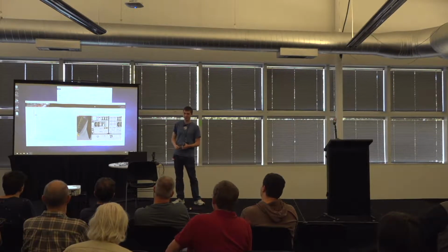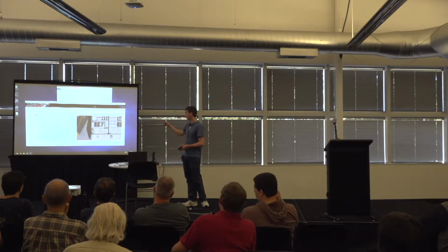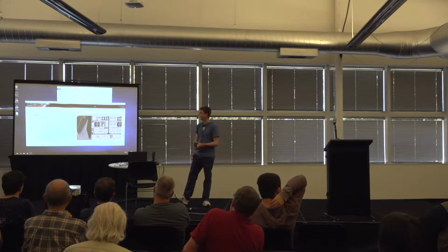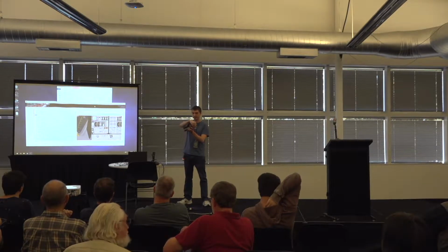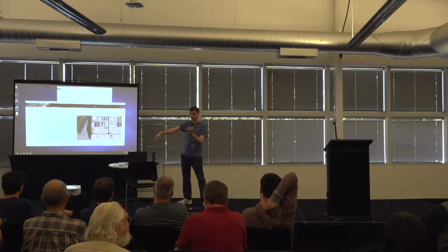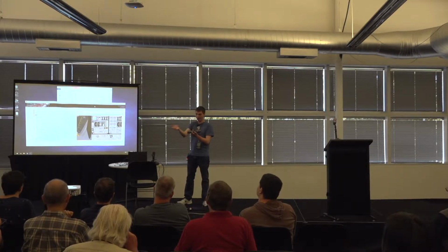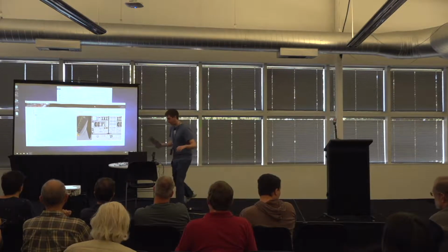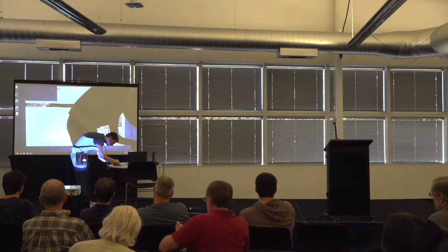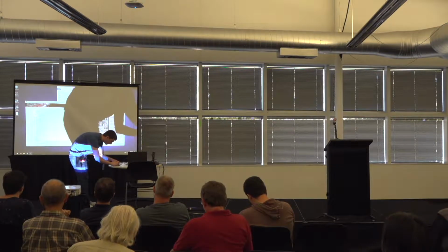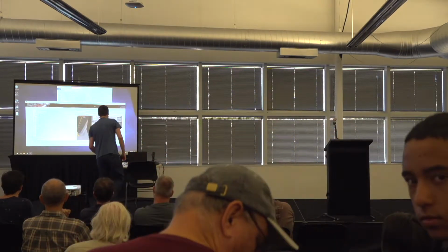NASSP implements the Apollo spacecraft down to a ridiculous level of detail. Most of the subsystems are modeled relay by relay. And normally it runs an emulator of the AGC. But I have modified it to, instead of using the emulator, talk to my debugger board so we can get inputs to the real AGC and out, or in this case, into the FPGA version and out. So I'm going to go ahead and plug my FPGA in. And we'll get started.